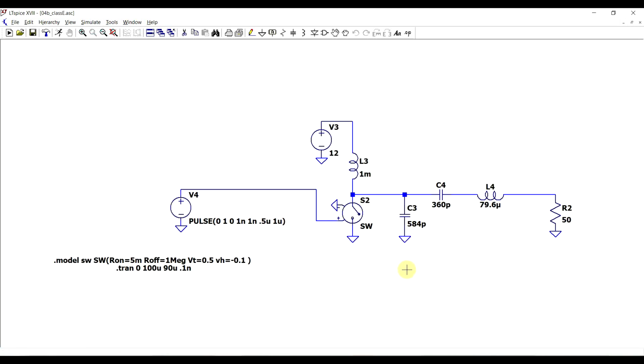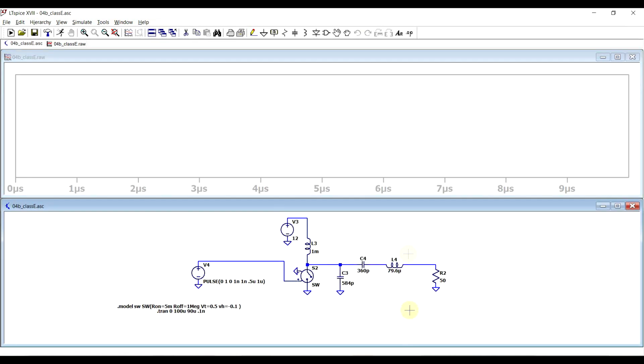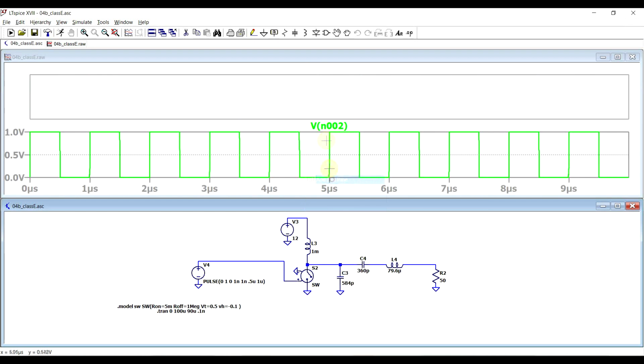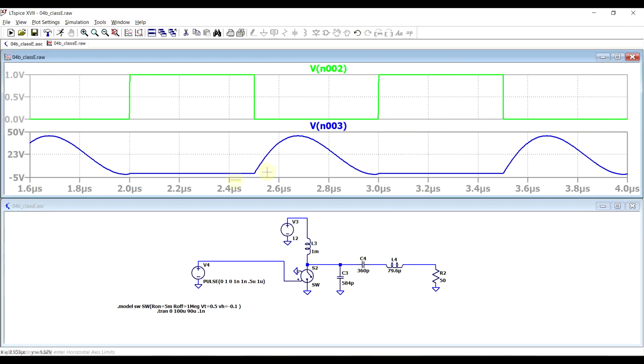Now, one other notable example here is the Class E type RF amplifier. So I will be analyzing this type of circuit in more detail sometime in the future. However, the interesting thing about this circuit is that since the transistor is driving a resonant load, so let's just pull up the various waveforms. At the moment of transitioning, we have almost 0 volts in the drain, so we do have 0 voltage switching on both slopes, so we're not getting losses from that.